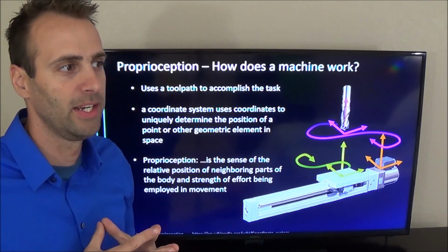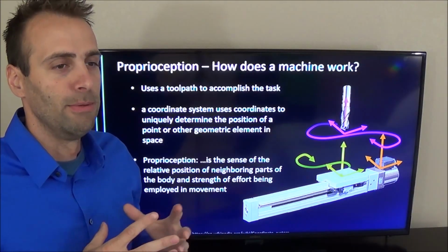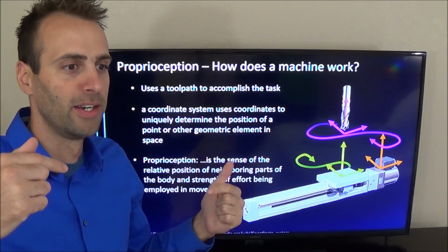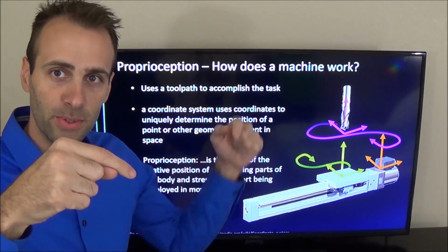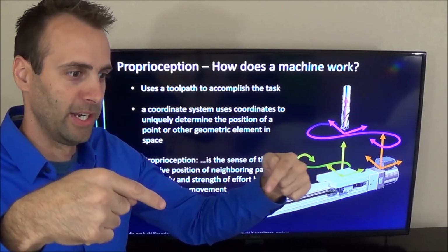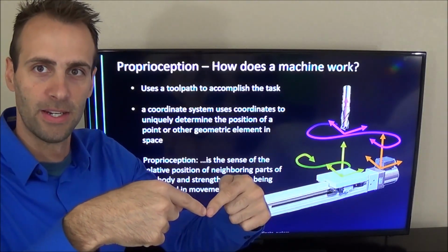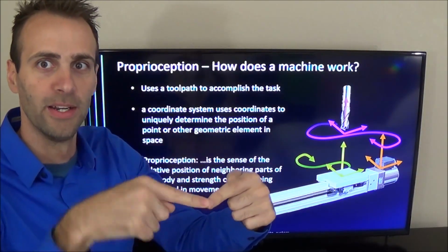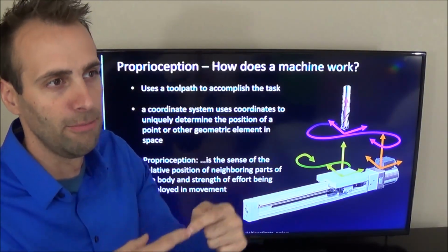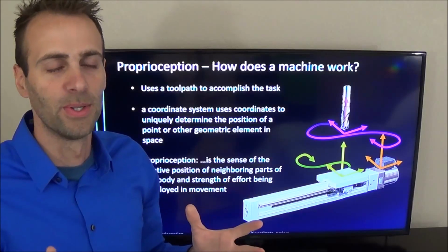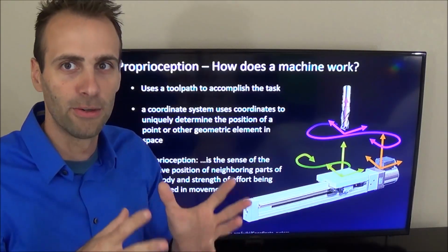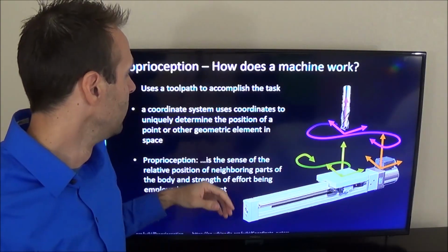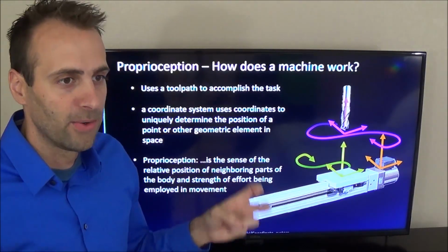When we say, take me to this place, or align this point on the tool and this point on the part, that's not good enough. We have to say, align these 2 points and then orient in this way, right? Maybe on some machines you don't have control of that, but in the error model it matters, and we'll see why later. So that's the advantage of a coordinate system.